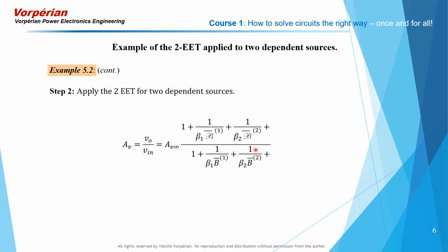Now, we know that this is not complete, and these two dependent generators will have to come back in pairs. Beta 1, beta 2 in the numerator, and beta 1, beta 2 in the denominator, again appearing in the little denominator here and here, only because their reference values were taken as infinity each. Now, the first one, beta 1, is reinstated, accompanied by its null inverse gain, just like here. Beta 2, on the other hand, is reinstated with its null inverse gain, but this time, when you compute the null inverse gain for beta 2, beta 1 is going to be in its opposite state in relation to its reference state. In its reference state, it was taken as infinity, so now when you are computing script beta 2,1, you have to set the value of beta 1 equal to 0.